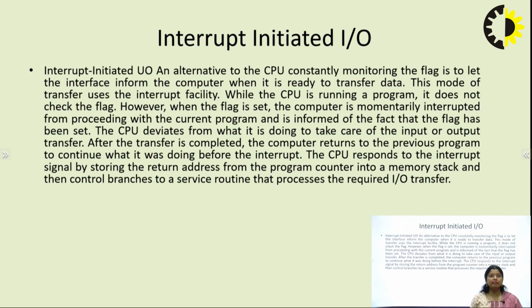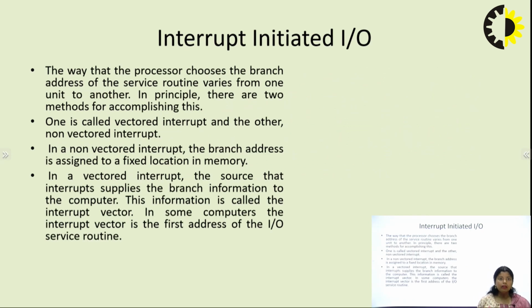One solution is interrupt initiated IO. In interrupt initiated IO, only when the IO device has data will the CPU transmit the data. The CPU is not busy always checking the status register flag to see whether the IO peripheral device has a particular data or not. That's why it is called interrupt initiated IO. Interrupt means breaking whatever CPU operation is being performed.